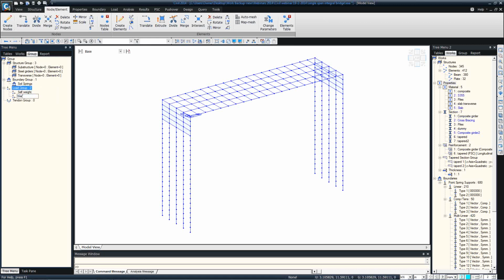Then wet concrete, and then earth pressure. Sometimes, instead of modeling the boundaries for the abutment, we don't go into the abutment soil structure interaction. Rather, we apply the pressure on both the abutments and ignore the boundaries. That is also another way of applying earth pressure and surfacing.